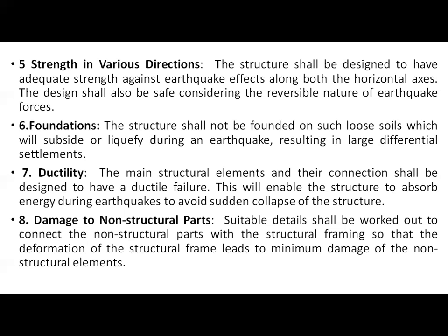Next one is the foundation. So what is this foundation? The structure shall not be founded on such loose soils which will subside or liquefy during an earthquake, resulting in large differential settlement. Okay, so this point is very important, because of the foundation only. In unit number 1, we have learned this liquefaction concept. So what is the liquefaction concept?